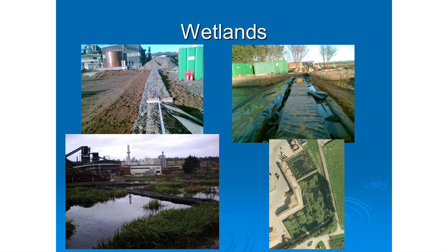That's just pictures of construction of the wetland. It's all lined. Perversely, there's some superb sand and gravel underneath this site that is ideal infiltration country. But because of the pollution in the runoff, we're not allowed to let it soak into the ground until it's been through the treatment system. So that's why the wetland's lined. And then you can see in the bottom, that's a photograph about 4 years after it's been constructed. And you can see it's a well-developed wetland now, and it is working effectively.